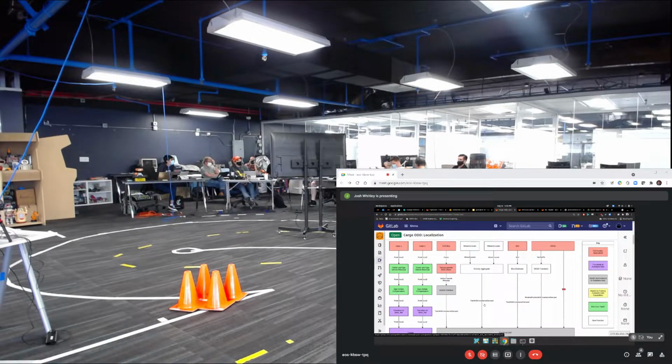Unfortunately, it's actually really, really hard to tell when NDT matching fails. That's a really hard philosophical problem to solve, or logical problem, however you want to look at it. Because you can say, I want to try and match X number of times, but what if it matches and that's not the actual location you're at? You have no way of telling that that's not the actual location because you got a match, right? There can be some certainty associated with that match, but it's never going to be zero, so you can't know when it fails.